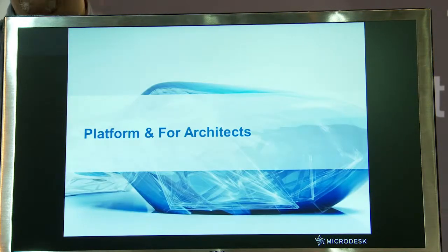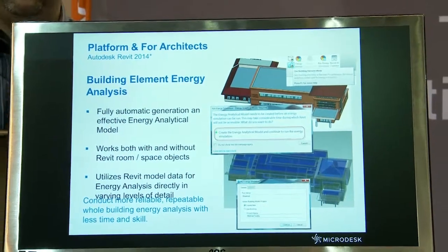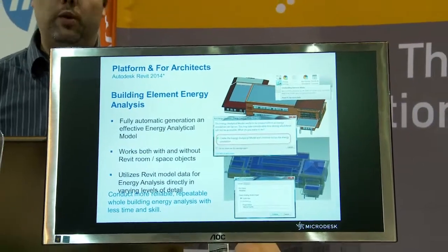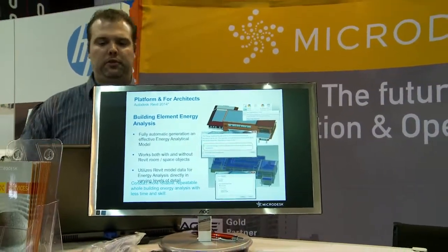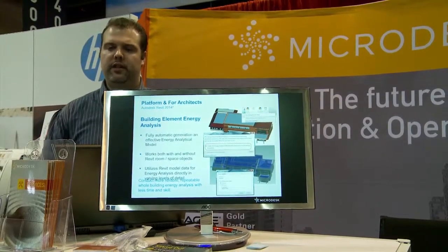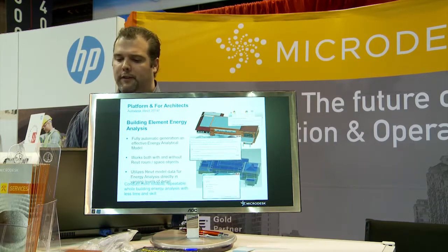So in terms of what's new that is applicable to all trades, but very specific and unique to architects, let's start with the building energy analysis feature. It allows you to now do something that would take you forever in the past, which was generate a building volume that you can leverage for creating energy studies. For anybody that's ever done any kind of simulation, you would require a building that is sealed and airtight, so that you don't have any areas that are left out.